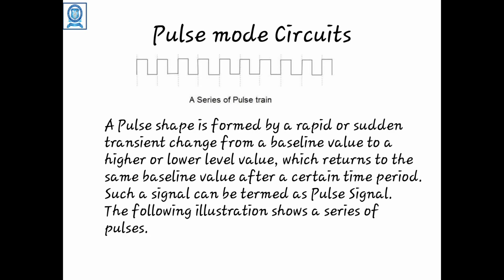Asynchronous sequential circuits in general are of two types: one is fundamental mode circuits and the other is pulse mode circuits. A combinational circuit attached with delay elements connected in feedback loops is called an asynchronous sequential circuit.